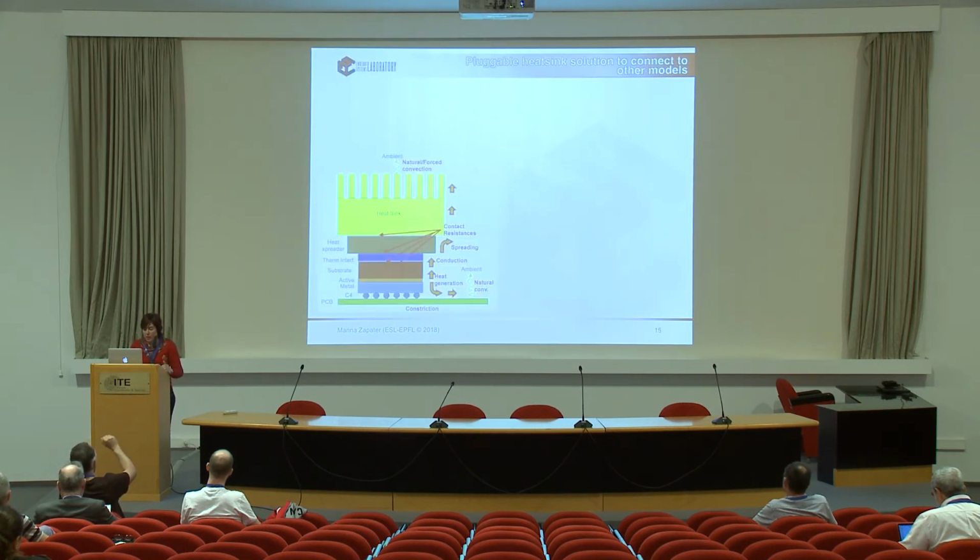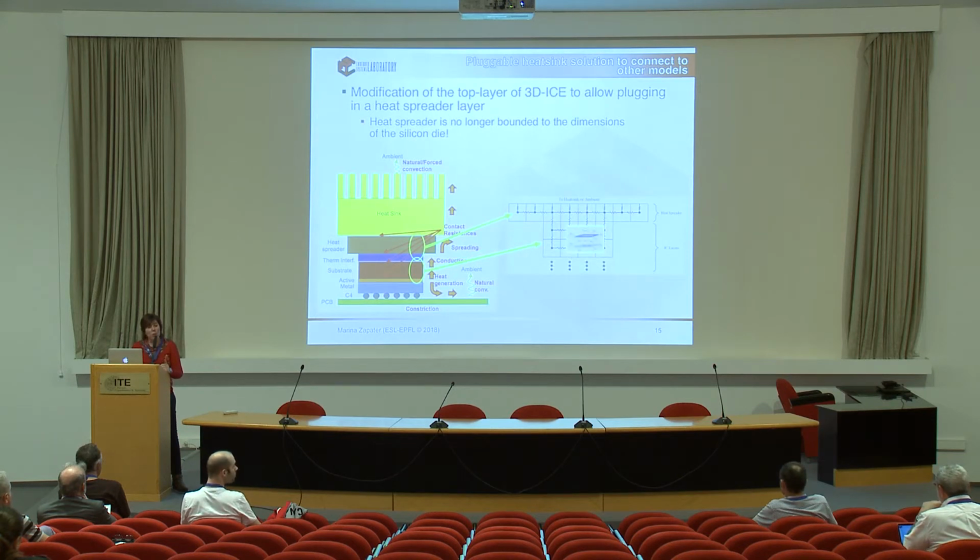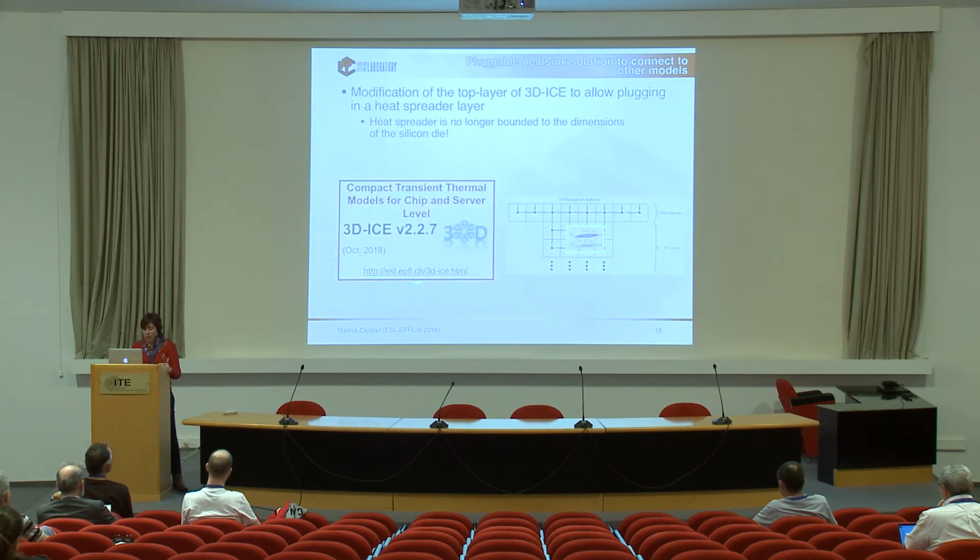So basically, the first thing, which would be the pluggable heatsink solution, what it does is, as I was saying, simply simulating, as we were doing before with 3D-ICE, but at some point, instead of keeping on simulating the upper layers, the heatsink plus the fan, we will be connecting to some other simulator.